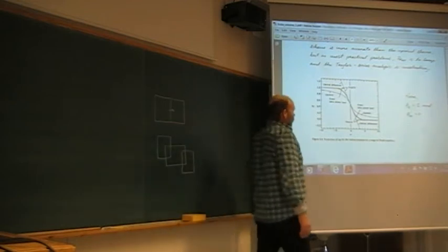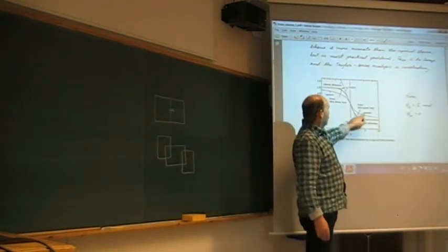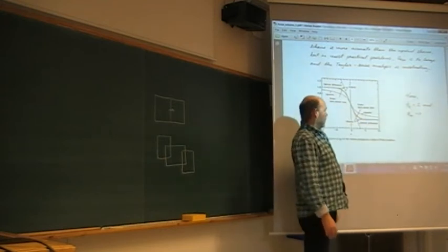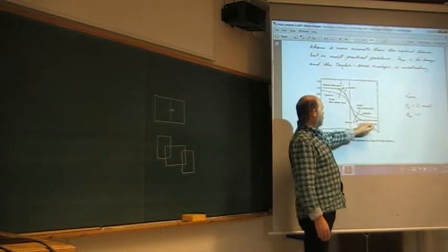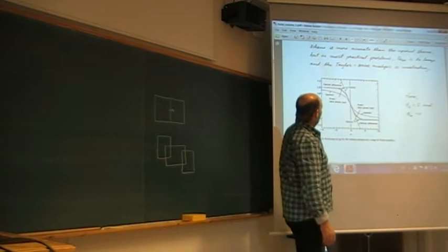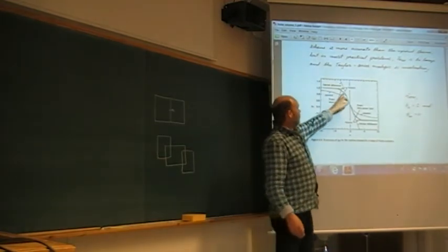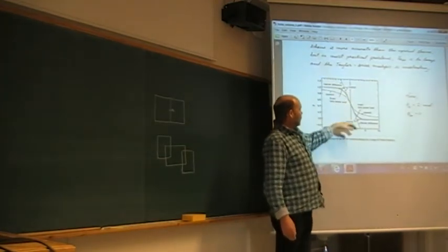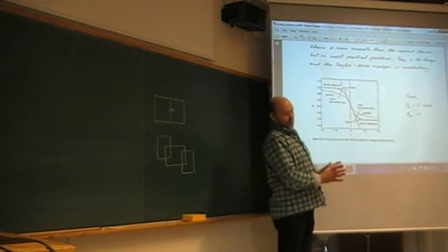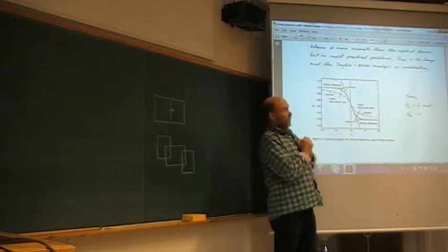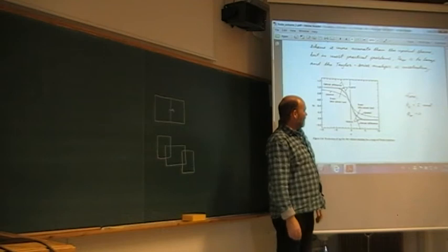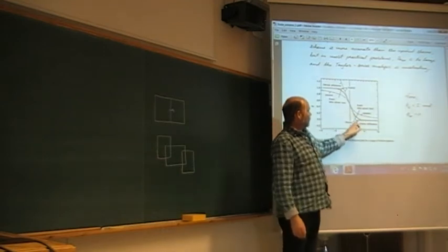The first order upwind is stable for any cell Reynolds number. It was unconditionally stable, but far off what it should have been. The exact should be here somewhere. A hybrid scheme can easily be designed. You use the central scheme if possible, but if the local cell Reynolds number is bigger than 2, you switch to the upwind. But it's not a nice behavior either.